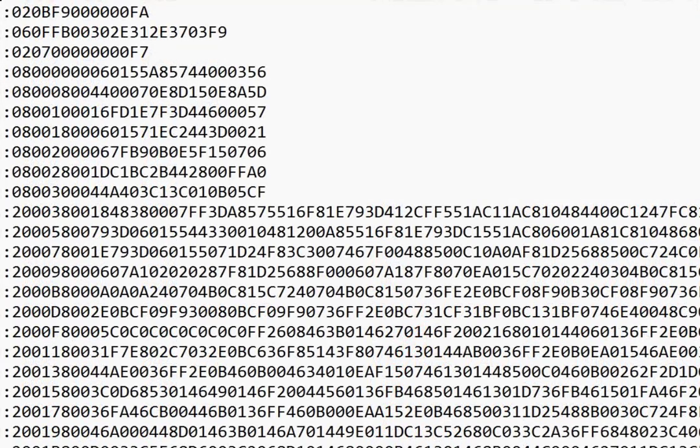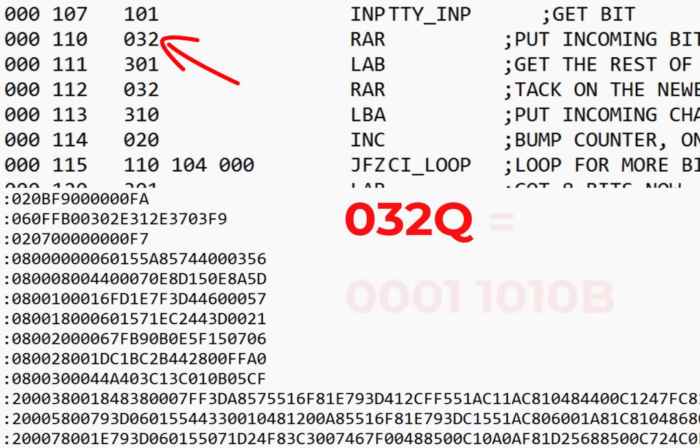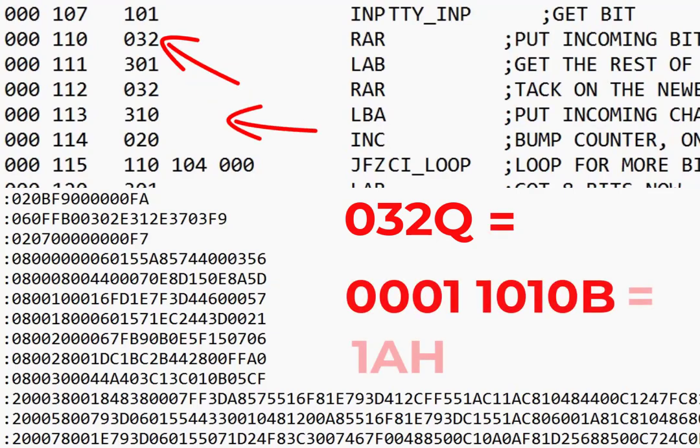Then we take that source file and we assemble it, and the assembler creates the output file, for example, an Intel hex file. In doing that, the assembler takes the mnemonic and creates the machine instruction, which is the binary data that the processor can actually interpret. And it's that machine instruction that sets the internal configuration and allows that instruction to be executed by the processor.